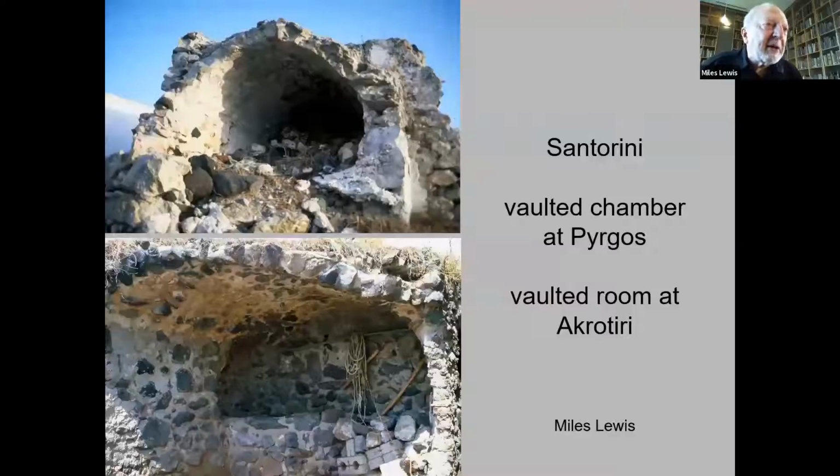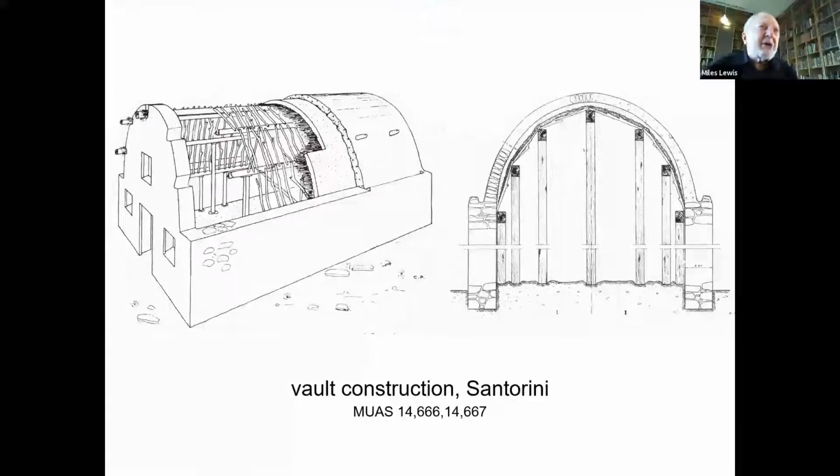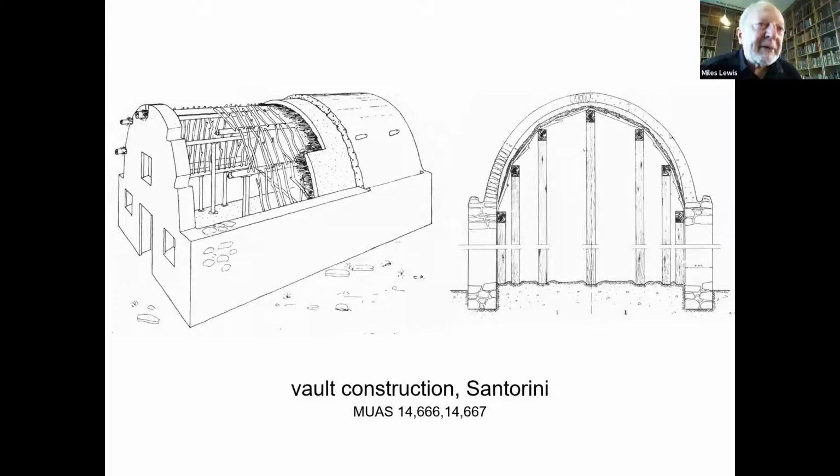There are some broken down ones. And they're built without using elaborate carpentered formwork. They use this sort of vernacular fashion. So you make a framework with these rough timbers, and then you build it up with reeds and other material to make it smooth, probably with plaster then, and then you place the concrete on that, to get a true surface. And it's possible that much of the Roman work would be done in a similarly ad hoc fashion. We just don't know because we haven't got the evidence of surviving formwork.